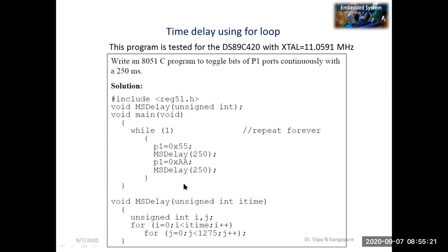In other words, what this program is doing is continuously toggling port 1 bits or pins with a delay of 250 milliseconds in between. Okay, and that is being asked here. In this way also we can generate the precise delay required.